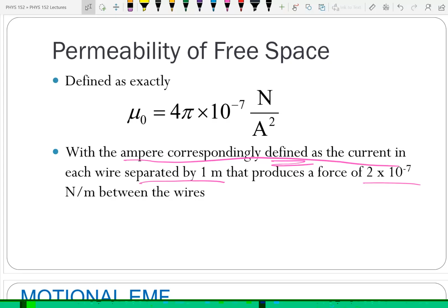If you make them cross at perpendicular angles, you'll have very little interaction. If you make them parallel, you'll have significant interaction and interference. So I had to make sure, okay, I've got to cross the power line. I'm not going to go parallel with it, not just cross it sliding. I'm going to come like this, go straight across, and then go on the way I want to go.